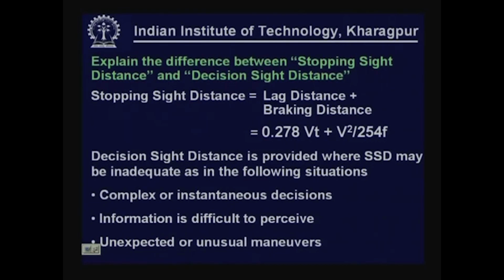Under those conditions, the perception reaction time assumed for stopping sight distance calculation is not adequate. There one has to go for decision sight distance.